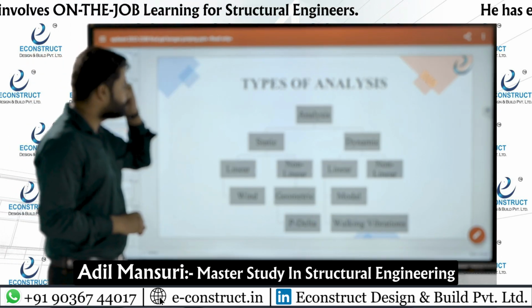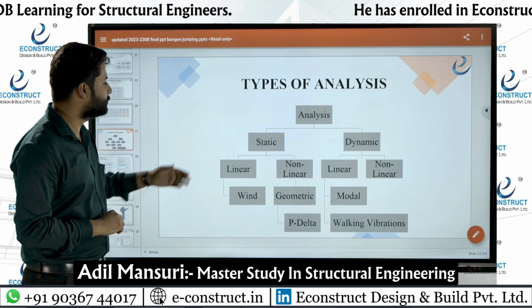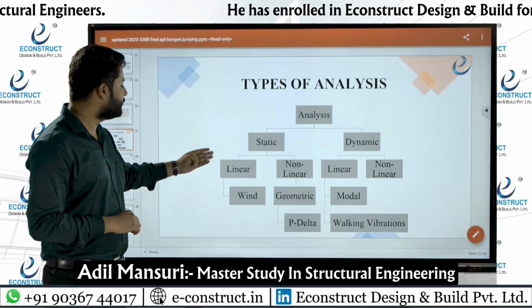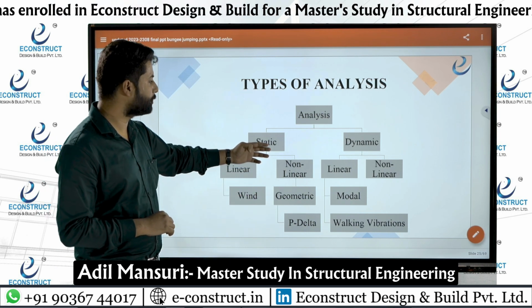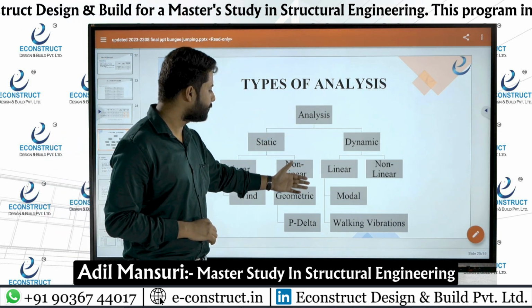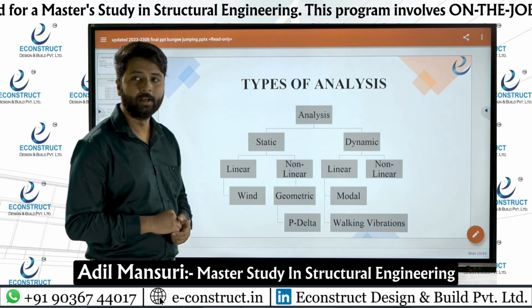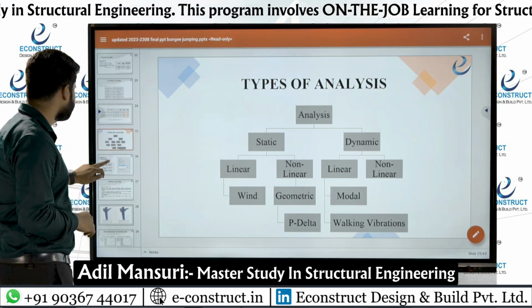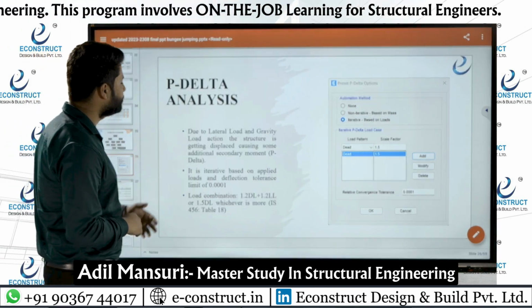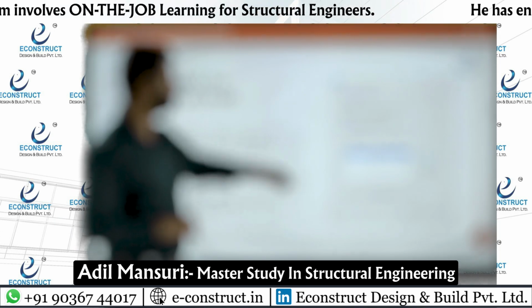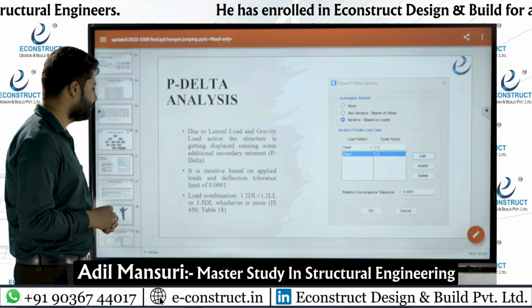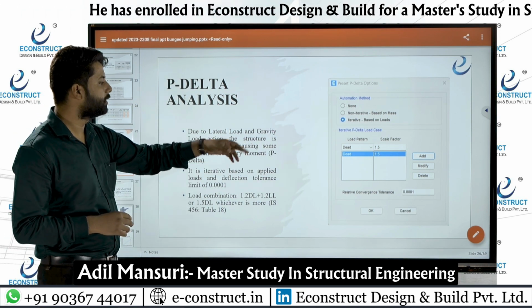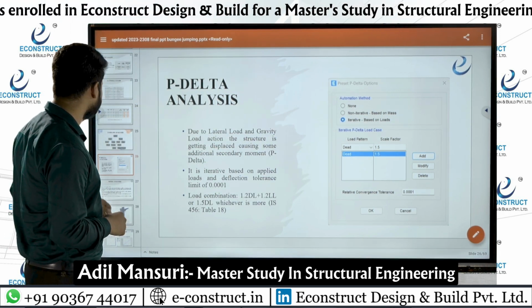Here are the various types of analysis. As you can see, static, dynamic, linear is wind, non-linear is geometric, P delta we have considered in this project, and dynamic effects, linear model, walking vibration we have also considered. So this is the P delta analysis. We have considered dead load scale factor 1.5. Majorly governing it is there, 1.5 times dead load.